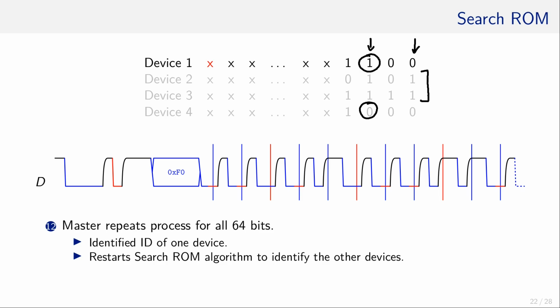Since there is no hardware support for the 1-Wire in the ATmega, there are 2 options. First, a dedicated chip is integrated into the system that is able to translate between the 1-Wire and the supported protocol such as I2C. Or second, the entire functionality needs to be implemented in software.